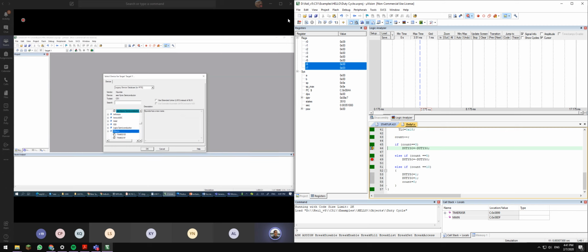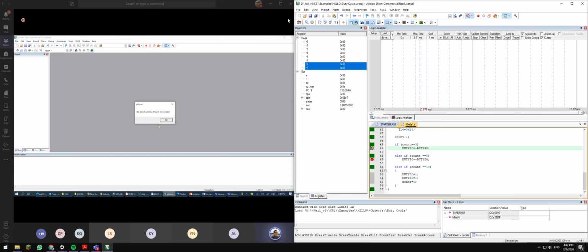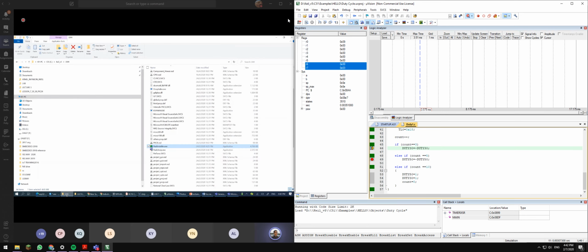Okay, Maxim, it can support a lot. Any microcontroller in the MCS51 family can be supported. And one more thing I want to say is how about the ARM microcontroller? I believe I also asked you to install the MDK. Once you install the MDK, you go to Keil uVision 5. This is recorded, no worry, you can come back to this. Go to UV4, then you can click the pack installer.